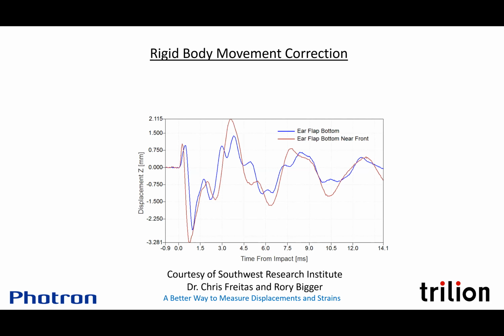Okay, next question. How would you spray speckle on aluminum foam? Aluminum foam. Foam, because of the little caves, or the non-flat surface. I've done different types of foam. If it has very high porosity, like an aluminum foam, the best approach sometimes is to use a single camera looking straight at the specimen for a compression test. We just added some speckle within the porosity, and we actually got decent results.